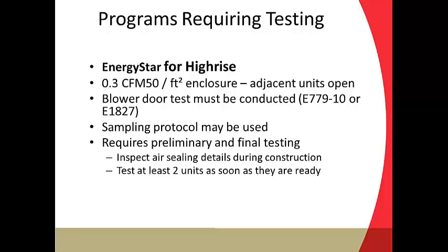So if you wait till the building is complete before testing, that's not really setting up your customer to pass the test. You need to get in there as soon as a couple of units are available, find where the issues are so they can be corrected right away before the rest of the units are sheetrocked, and on the other floors work through those details as you're going up.